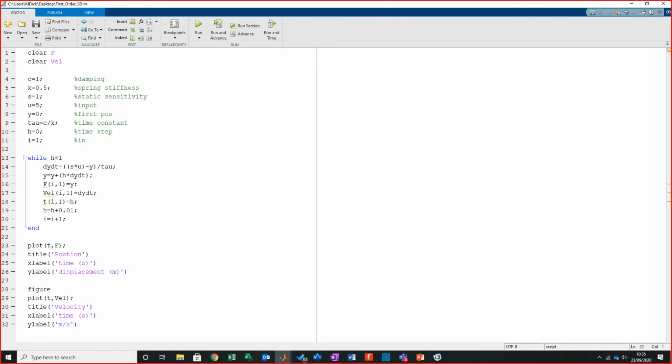So what I'll do is I'm going to type subplot, and I'm going to go 2. What this will do is allow me to put in a 2 by 1 grid, in position 1. So this tells me that there'll be 2 rows on there with 1 column, and I'm using the first one within all of that. So I'm going to close that,